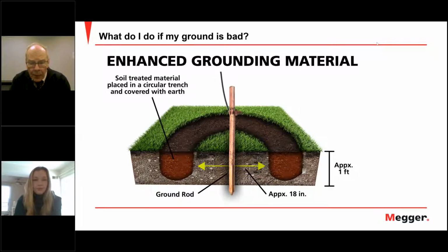So the most common way is to either drive a deeper rod. So we see a picture of a rod here. You can put a coupler on top of that and then another rod, and use some sort of a hammering device and drive it into the ground. That's one way. And then the other most common way is to add more rods in parallel. And so the difference here is probably, in general, the really best method is the deep driven rod. Of course, you get a room full of experts and they'll argue this for hours. So it's not cut in stone.